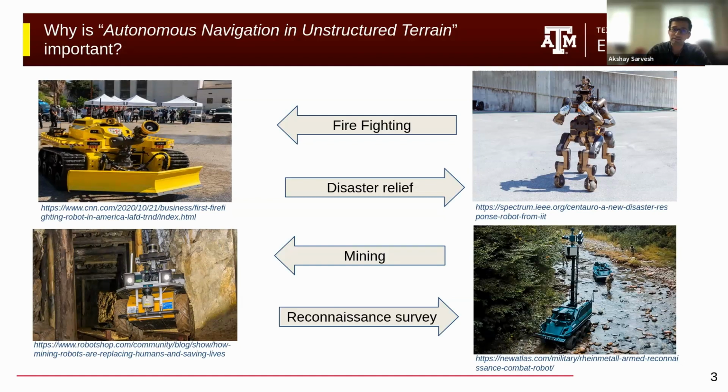One common aspect of all these areas is the environment happens to be quite unstructured. It could be filled with negative obstacles like potholes, or it could be obstacles where there are hills, or there could be even obstacles such as trees and shrubs. You cannot have one common algorithm for perception most of the time that can give you a holistic view of the environment around you. In this type of scenario, you would need to rely on the acuity of your algorithm, the decision-taking capability of the algorithm to take you out of those tricky scenarios.